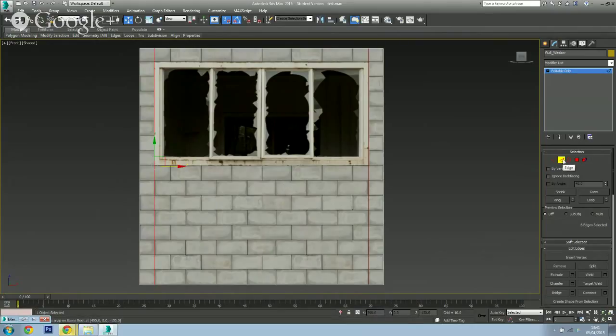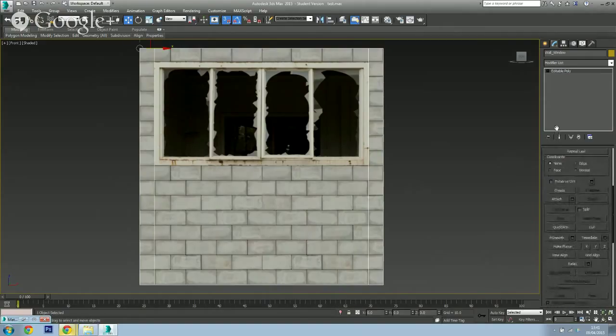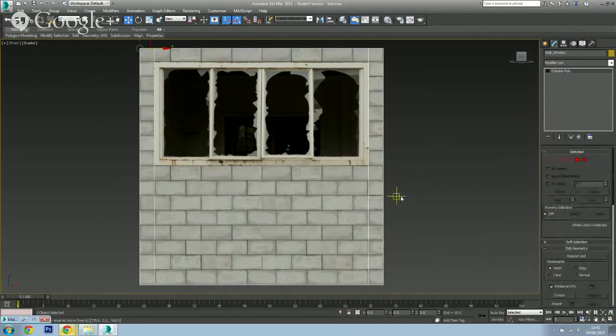Now, one thing that I've forgotten to tell you, and I've just remembered just now, I've been very lucky with the first cuts that I've just put in there. It hasn't edited the texture whatsoever. But sometimes when you are adding in all of these details, it can ruin the actual mesh for you, or sorry, the texture. To avoid that, make sure that you come down and you click on this Preserve UVs button here. What that will do is that each of the little extra cuts that you're going to put into your scene, this Preserve UVs will stop it from destroying the texture for you.